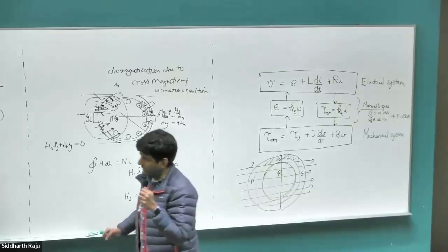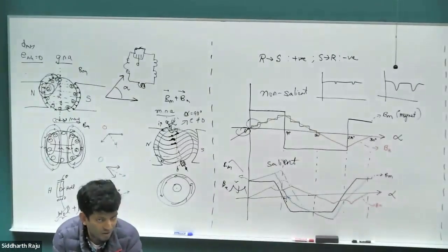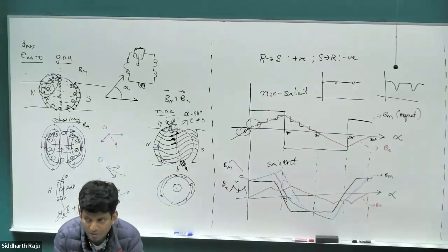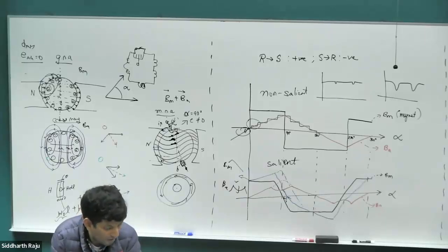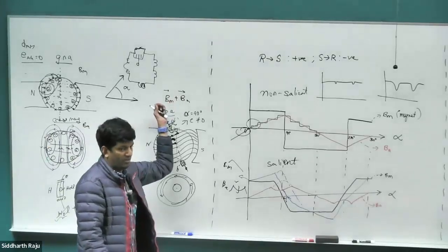There was one assumption that I made when I summed these two waveforms together. Right? When I took the black waveform and summed it up with the red waveform, can I do that to magnetic field? Can I just simply sum them up? When is that summation valid? When can you do superposition of magnetic fields? When they're parallel.